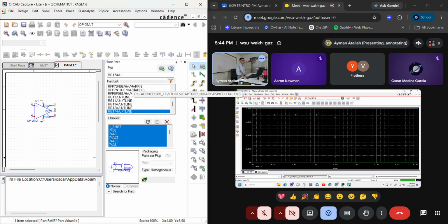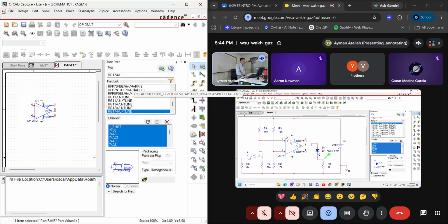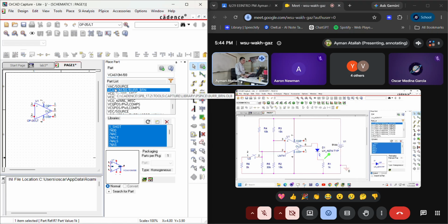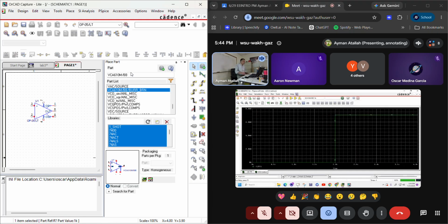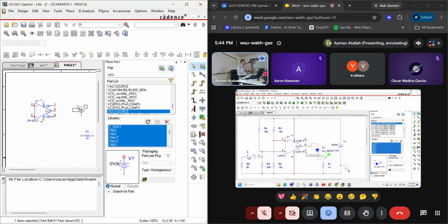Okay. The opposite way around, how do you connect this to this one and this to this? Because it depends how you connect these 2 points and the values you choose here. So I can delete this and connect this one to this one and this one to this one. If I do it like this and run the simulation, it will be off at the beginning. The light emitting diode is off at the beginning, then it will turn on. So it depends how you connect the light emitting diode, so how you connect the input of the operational amplifier. Because the operational amplifier detects the voltages and sees which is higher than which, and it generates output depending on the 2 voltages.